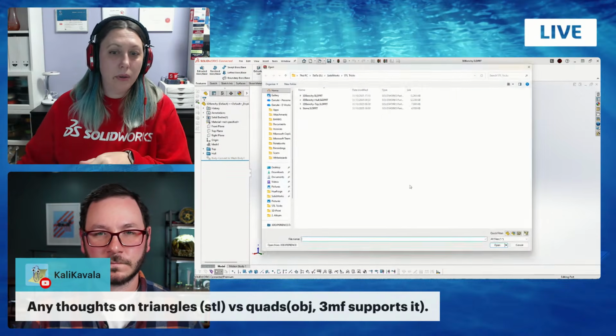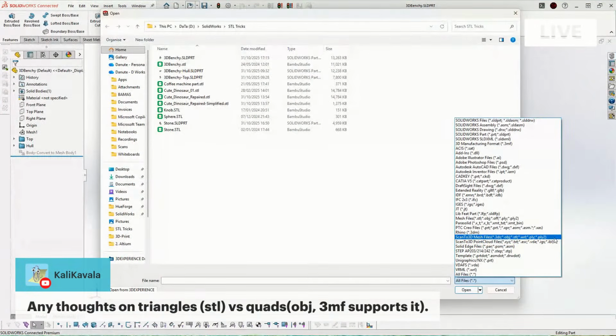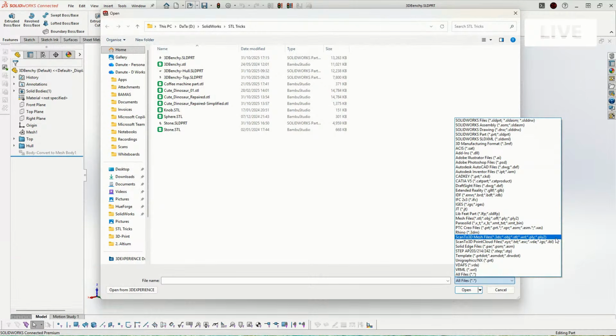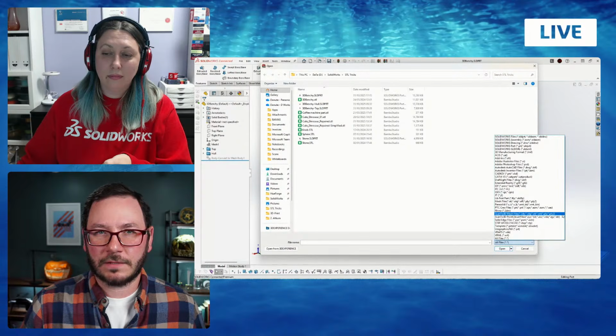So actually, if we go here, go on to scan to 3D mesh, you can see all the formats it can import. So it's not just STL. You have many different. You have OBJ, 3DS, and whatever. STL is just the most common one. Yep, that makes sense. And in my experience, if it's something that was modeled with quads, it gets imported as triangular meshes anyhow.